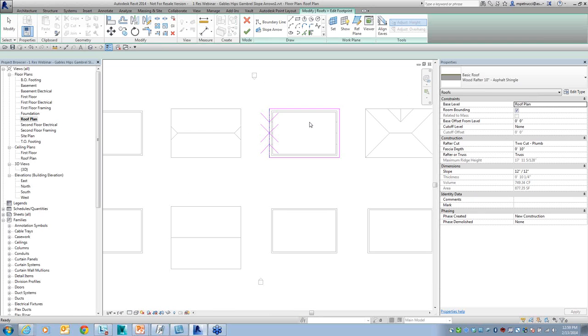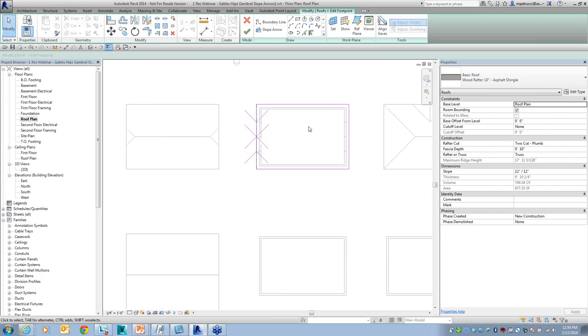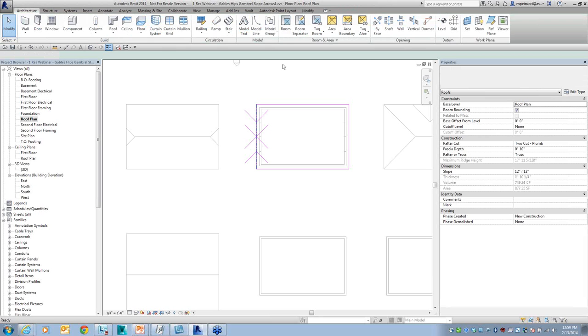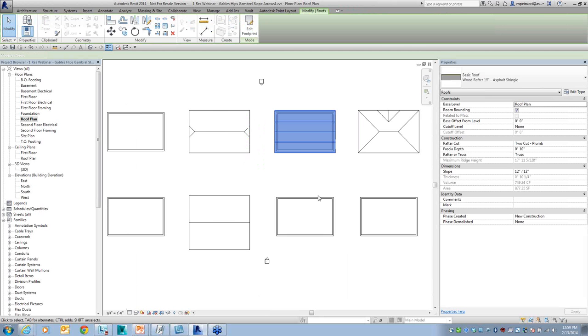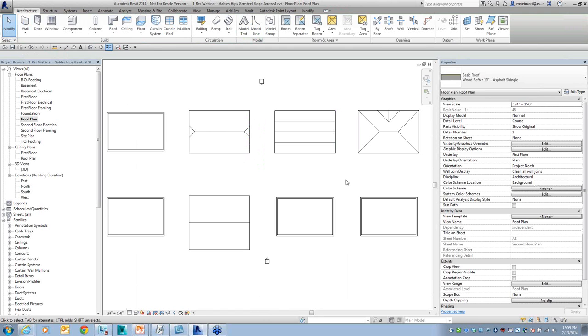For those of you who use AutoCAD Architecture, you can put in a double sloped roof inside AutoCAD Architecture. Well, in Revit, we can do the same thing here. And to be honest, it's easier to do this inside of Revit because I still have one roof, whereas inside AutoCAD Architecture, I have to work with roof and roof slabs. So I'm going to do the same process that you see here down here to create this roof. I'm going to start my roof command, and I'll use the pick wall tool with a 1-foot overhang.